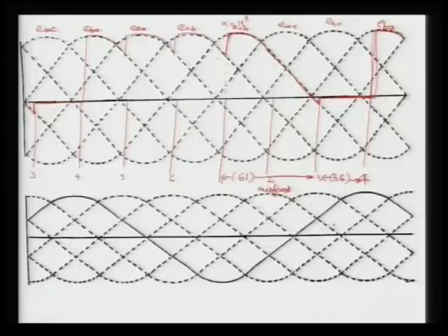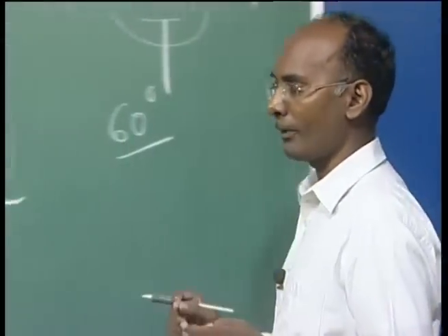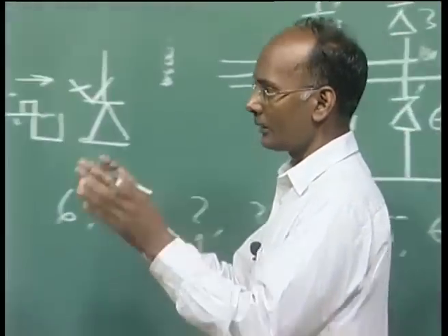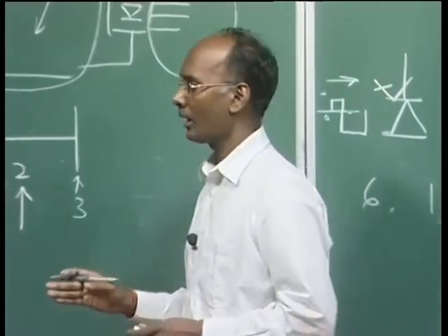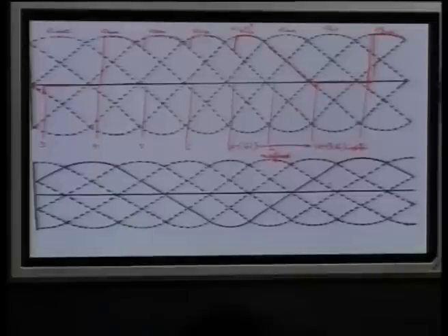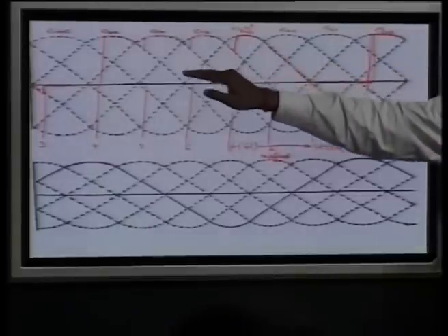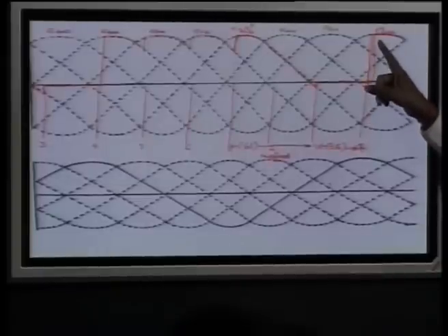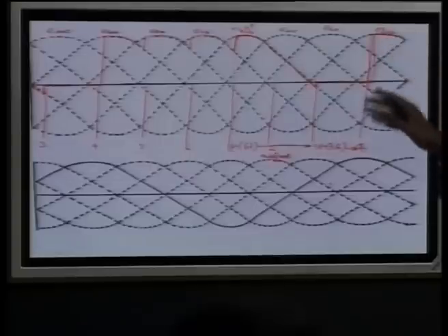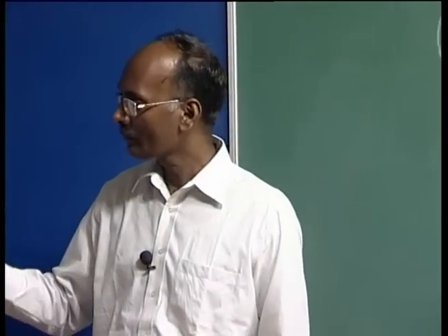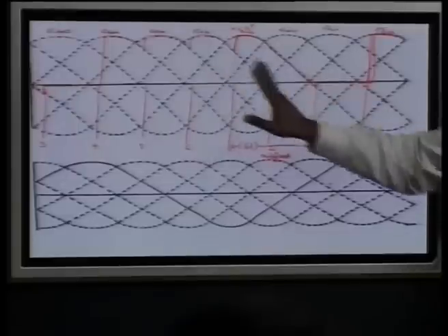So, you can see this is the DC output voltage in case of misfire when it is operating in the rectifier mode, because alpha is less than 90 degrees, and most of the time the voltage is positive. In this, you can see the problem is a huge surge in the voltage at the end of conduction, huge voltage is jumping, and this may lead to the puncture of some of the valves, and that is sometimes not desirable. So, here it is a rectifier.